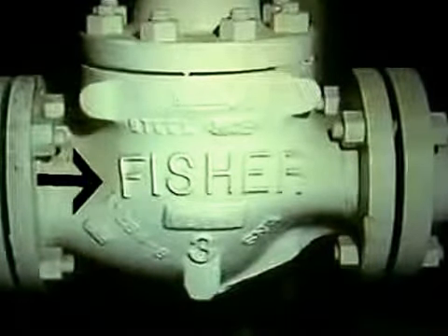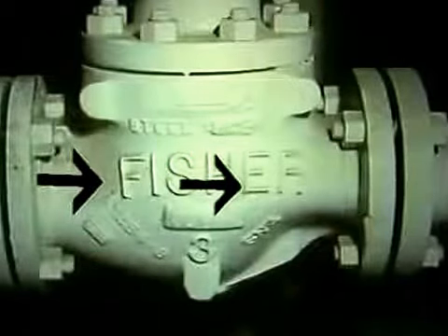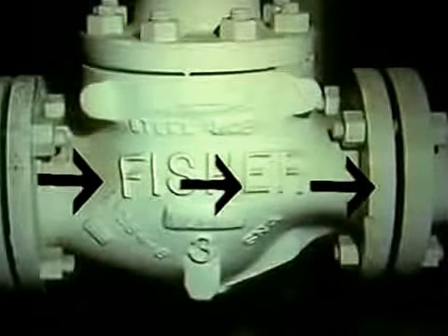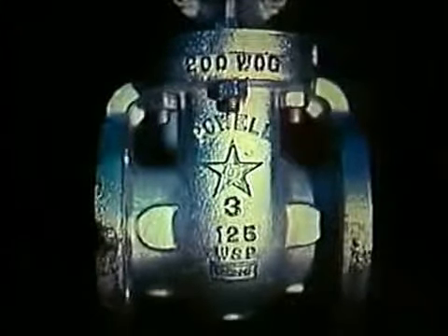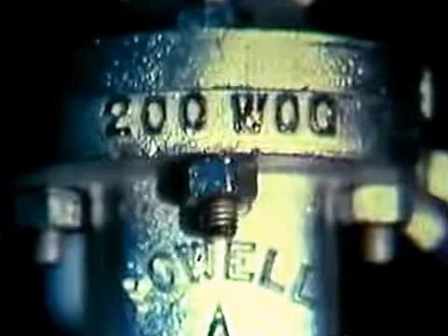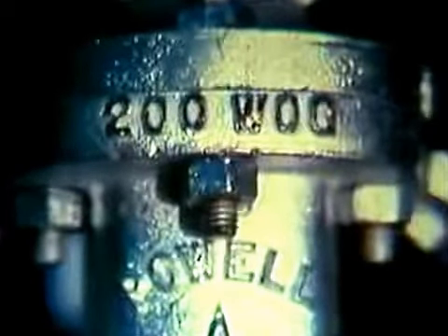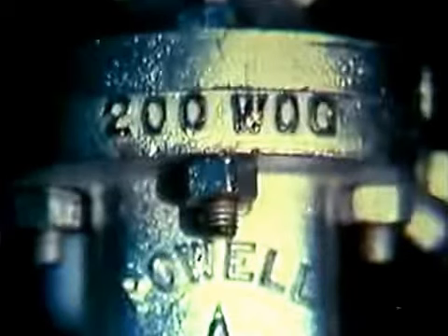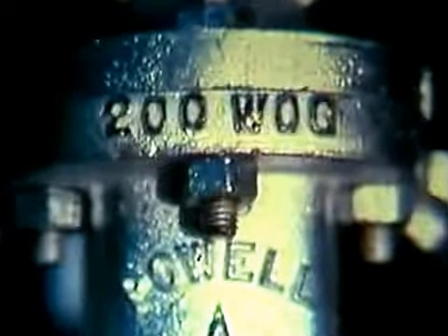Bridge wall markings on this valve show that flow comes in from the left, and then passes through the open area of the seat to come through this outlet. An arrow or set of letters also may be used to show the direction of flow through the valve. You'll find service markings on the valve too. These will indicate the operating range of the valve. For example, on this valve, the number 200 is the maximum allowable pressure that can safely be placed on the valve. These letters, WOG, stand for cold water, W, oil, O, and gas, G. They are for pressure ratings other than steam.